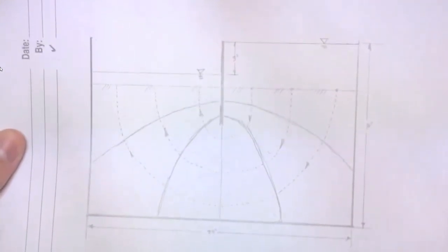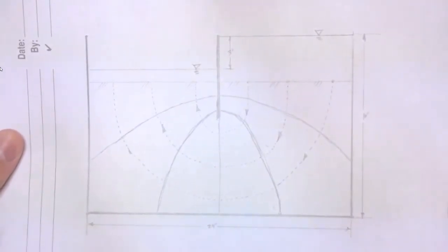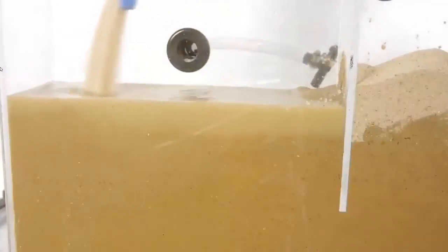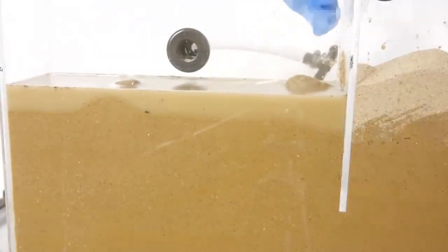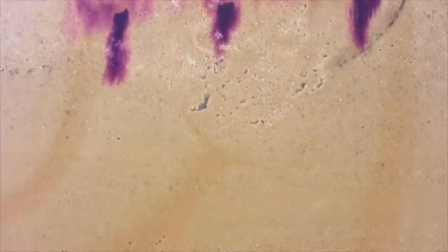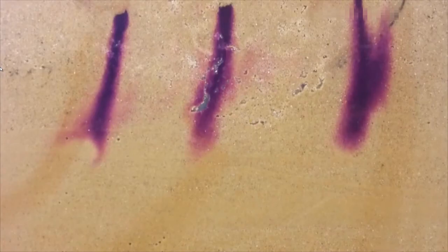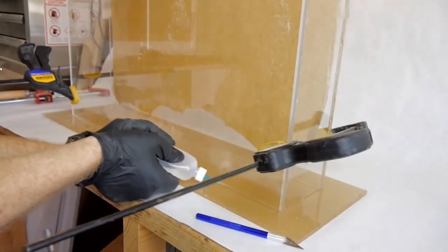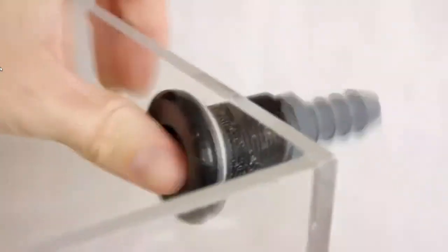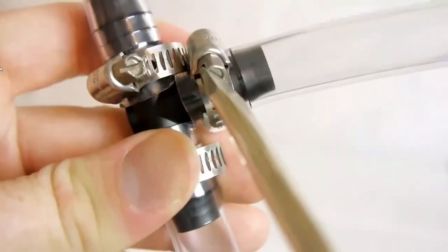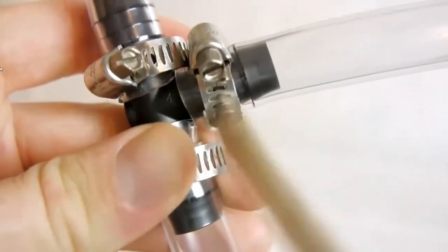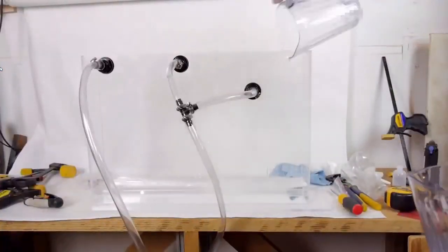These kind of simplified drawings make pretty pictures, but do they really reflect how groundwater flows in real life? It's always important to ground truth your calculations, sometimes even with real ground. This model is designed to do just that. It simulates the flow of groundwater around an obstruction to illustrate the morphology and velocity of the flow. It's made of 1/4-inch acrylic sheets cut to size on the table saw. Solvent welding is used to connect the acrylic sheets into a narrow box. All of the plumbing is composed of aquarium bulkhead fittings and clear nylon tubing. Everything was leak tested before the sand was added.